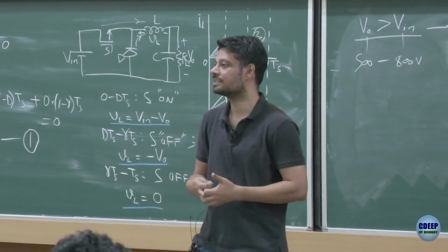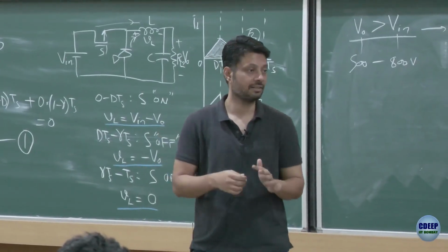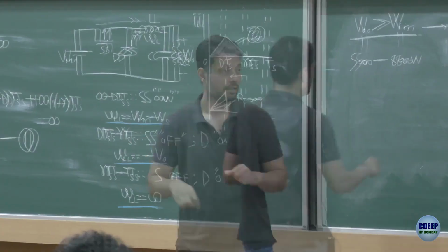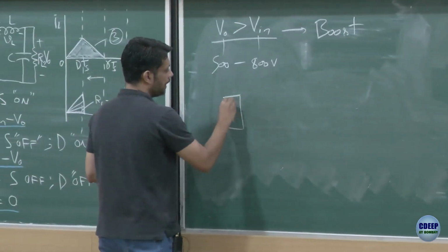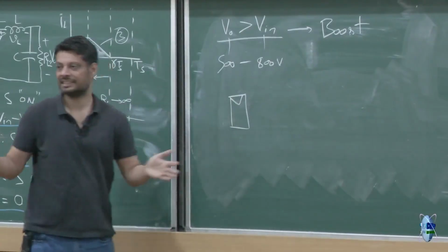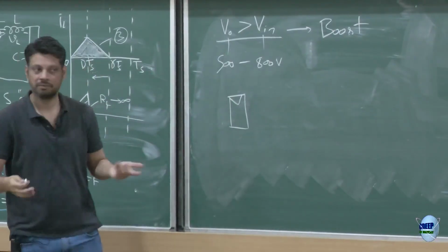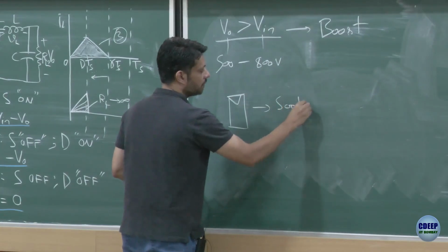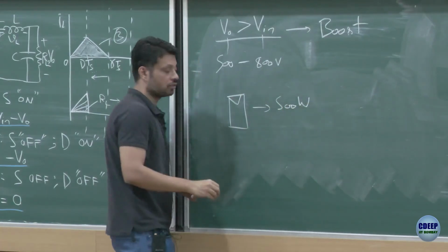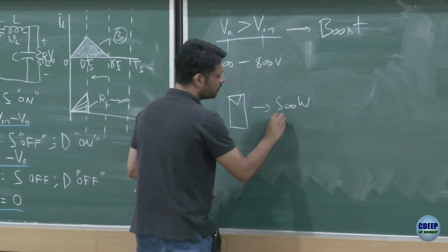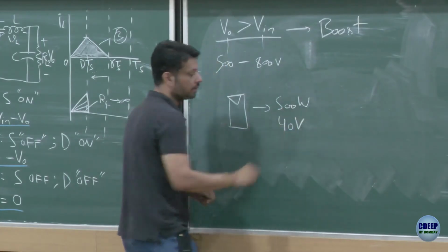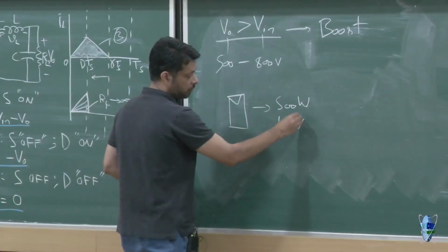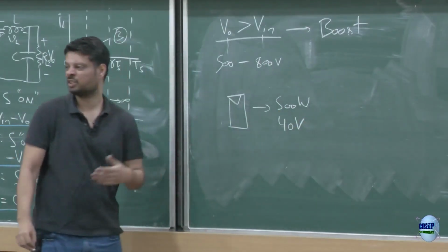It is solar generation. So, solar panels: one panel comes in different sizes and different powers. If I take one typical panel of 500 watt power, it comes with a voltage of about 40 volt. Of course the voltage is not constant, it keeps on changing.